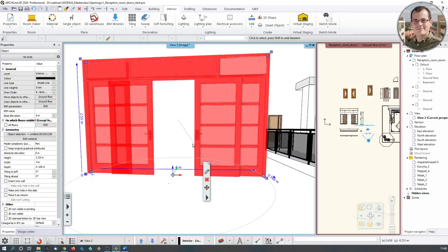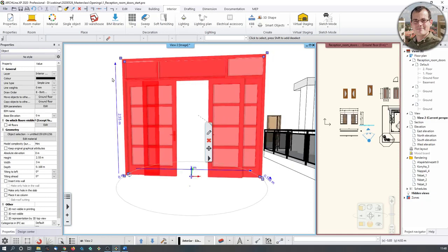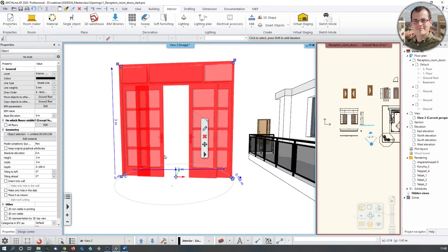So when you click on an element, you have two arrows, the blue vertical and horizontal ones, and it has arrowheads. And if you click on the arrowheads, that's the way the software is going to move the endpoint. So if you now decrease this back to 3 meters, then the endpoint is going to be snapped closer. So let me just hit enter, and you see this is how you can govern it. So if I change the size like this, let's say I change it to 3 meters, then this point is going to move upwards and not this point moves downwards, if you know what I'm getting at. So that is what you're looking for.